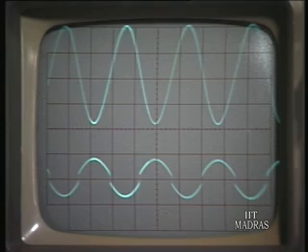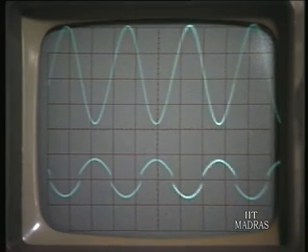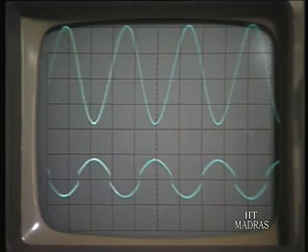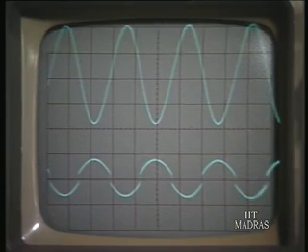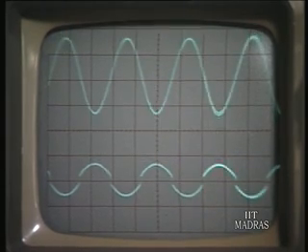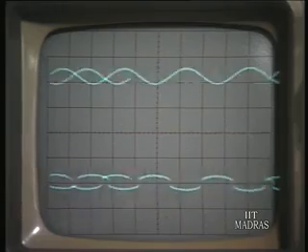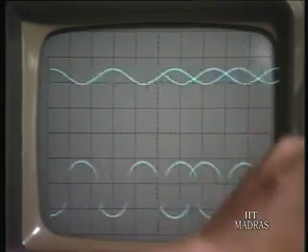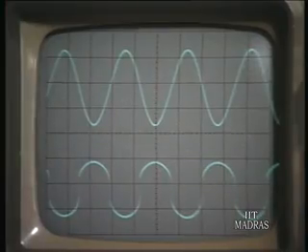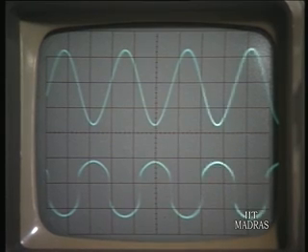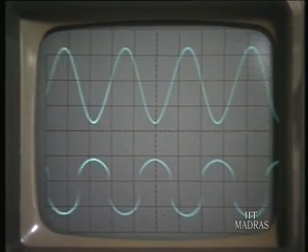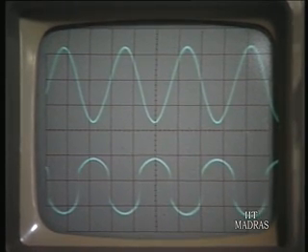It is jumping by an extent equal to plus V gamma and minus V gamma, and trying to follow the input. Even if the input is very low, make the input low, you can see that it is almost becoming a square wave. Increase the triggering. So the input is very low now. It is less than the cut-in voltage of the transistor, and further reduce the input.